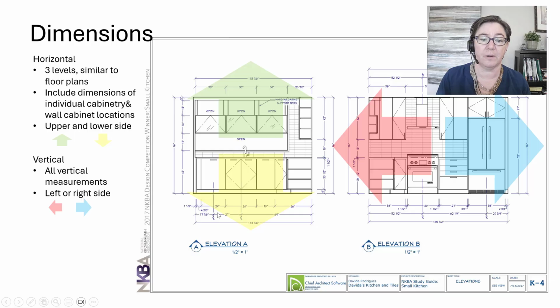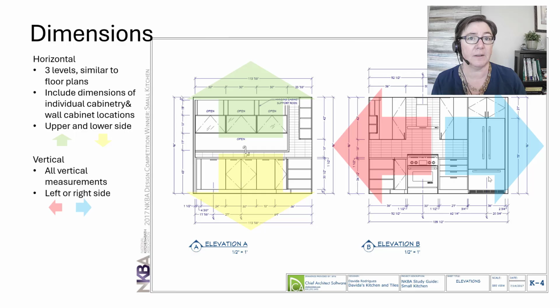Notice that just like on the floor plan, I suggest grabbing that dimension line and pulling it to the center of the item that we're dimensioning. You can see it right here as well, and here. It is far easier to read, and more clear than if your dimension just stopped out here. We can tell what is dimensioned more easily. Your overall dimension is that third line. If there's not enough information and you don't need those three lines, you just don't use it. Up here, we didn't have anything to center line, so we just left that one out.